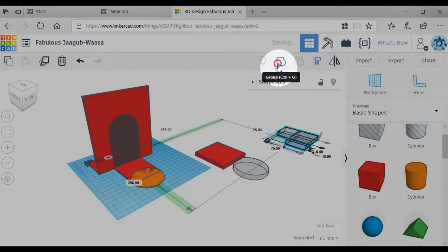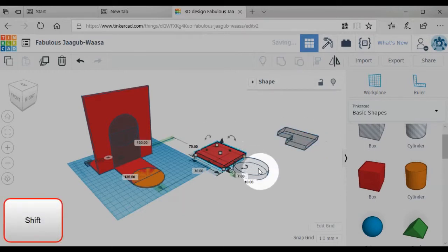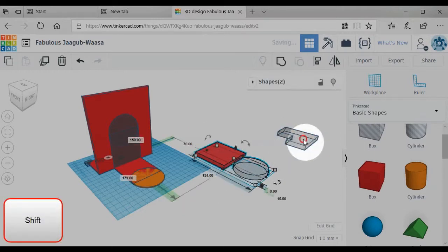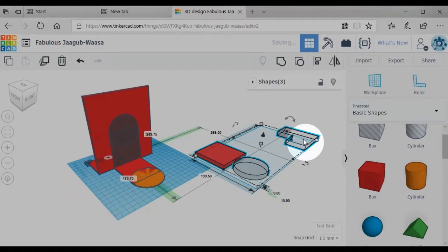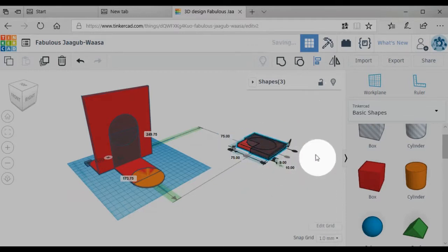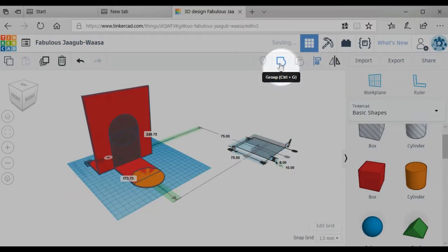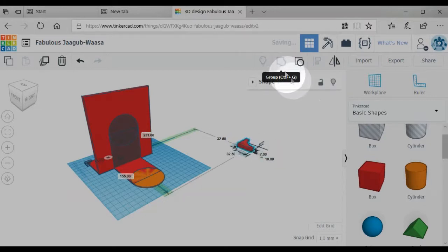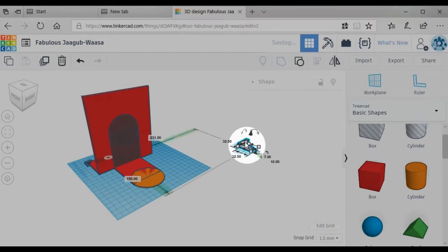Select the box that will be used to round the corner, the hole-colored cylinder, and the hole-colored corner piece that was just grouped together. Use the Align tool to center all three pieces. Using Group on the three selected pieces creates an object which can now be assigned the hole color. Before creating the duplicate, rotate the object around the y-axis by 90 degrees.